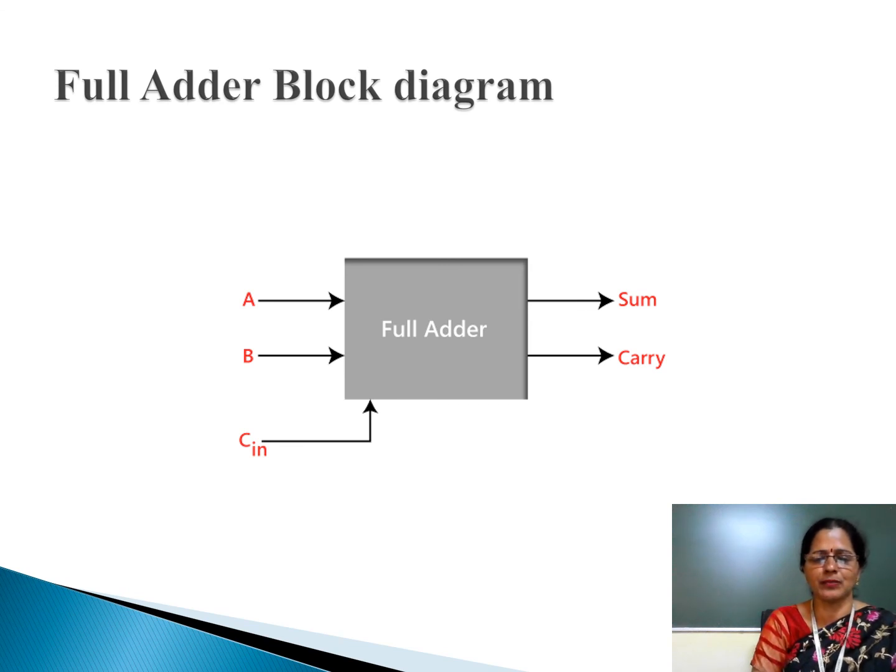Similarly, suppose your purpose is to add 2 binary numbers A and B, and the number of bits in A is 8 and in B is 8. So now you have to add 2 binary numbers each having 8 bit. In that case, considering 8 full adders, we can design that circuit, and that logic circuit is known as the 8-bit parallel binary adder.